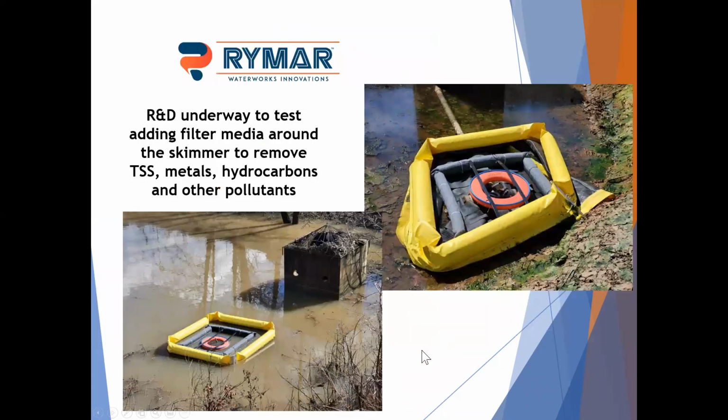So we've talked to a few of you recently, or previously, about doing some testing for TSS. We just finished the testing this week, and we're waiting on the results from the lab right now. But this is a prototype we've had in a basin. This is that same basin we showed initially as our case study. So we went out, changed the skimmer to our new model, and put in this filter system.